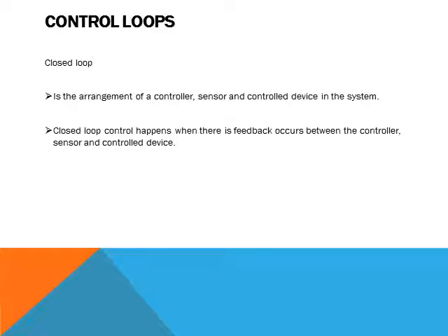Using the examples I have been using, we have a thermostat in the room set at 72 degrees. Our control point is 74 degrees. We have a 2-degree offset. We would bring on the cool air from the damper to try to bring our temperature down to the 72. So the controller would work upon the damper to bring that temperature down.